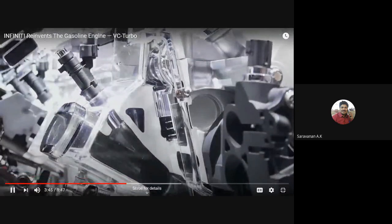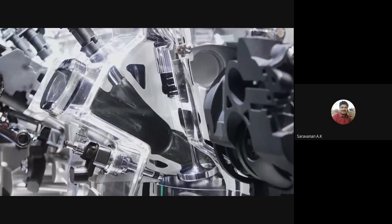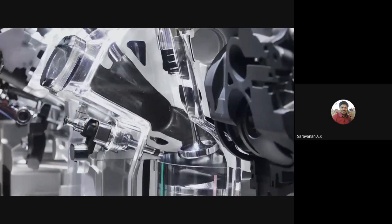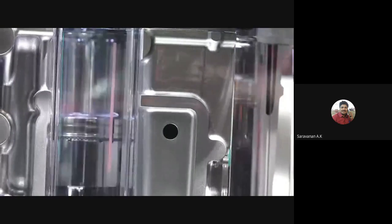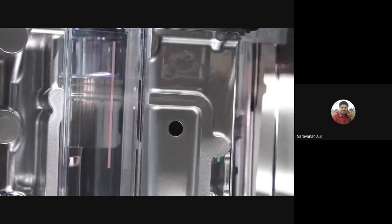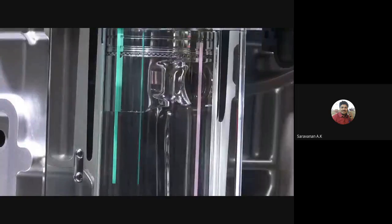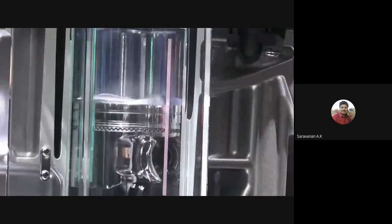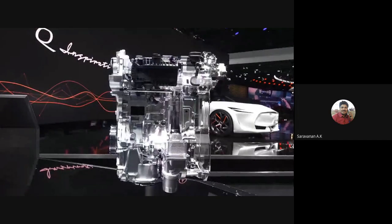Now, not only does it change the compression ratio, but it also switches from a traditional engine cycle to the Atkinson cycle by altering valve timing. The Atkinson cycle leaves the intake valve open for a short duration of the compression stroke, which means some of the air-fuel mixture is pushed out of the cylinder. What this does is effectively cause the expansion ratio, the piston moving down, to be greater than the compression ratio, the piston moving up, which allows the engine to get the maximum amount of useful work out of combustion.